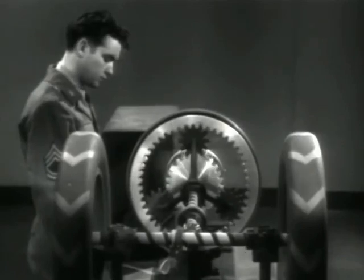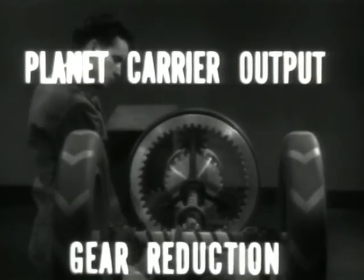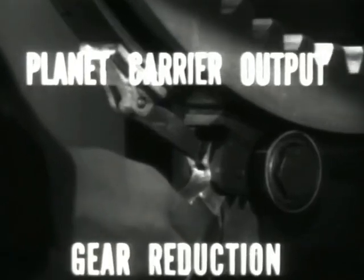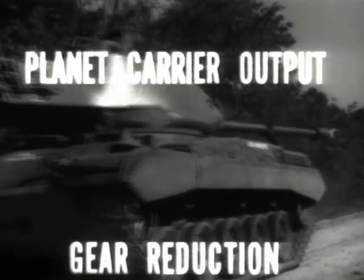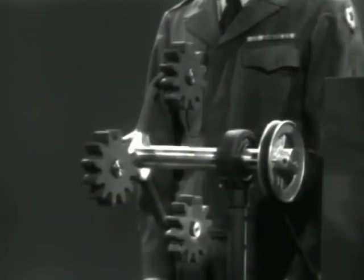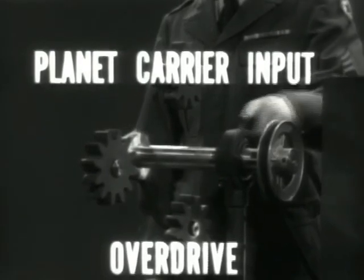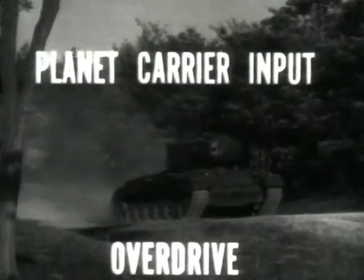Next is law number 2. When the planet carrier is the output and there is a reactionary, we get gear reduction. This sets our vehicle in motion. After this comes law number 3. When the planet carrier is the input, the result is overdrive.